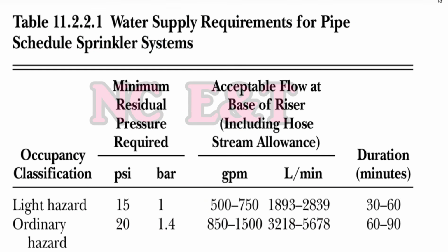This is a table from NFPA 13, table number 11.2.2.1. In this one, for the light hazard, we have a residual pressure of 15 psi, and we need the water in the reservoir to be sufficient for 30 to 60 minutes.